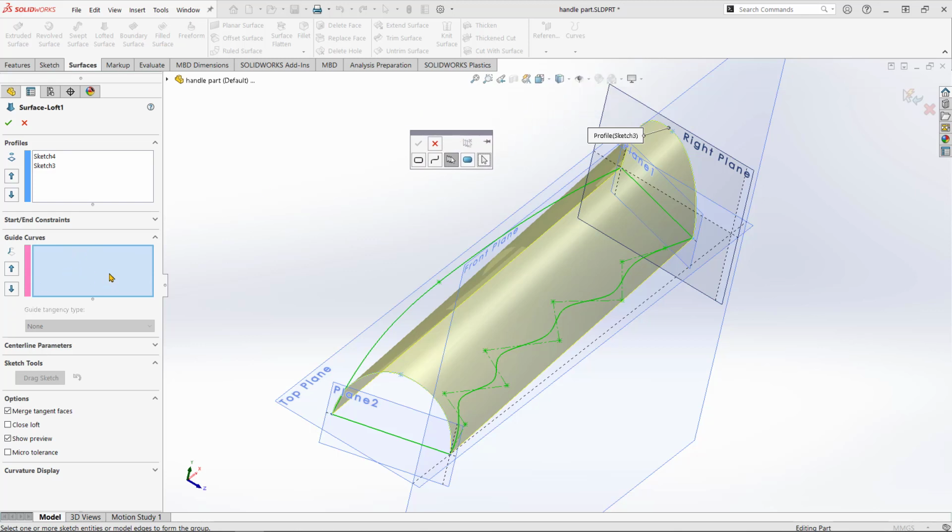So right click in there, tell it that you want the Selection Manager. This window is the Selection Manager essentially, and we're using this option, Select Group. What that allows us to do is select a single edge, as we're going to do, but if we need to, we can select multiple edges from a sketch.